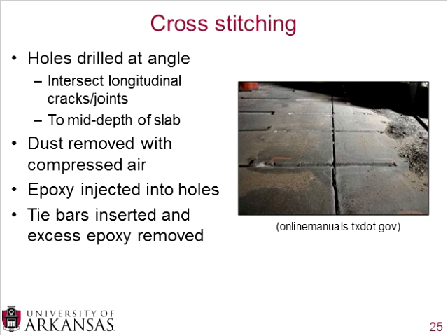So that epoxy will go from one side of the crack to the other side of the crack at an angle. Then you simply insert your tie bars and then remove any excess epoxy. And this will allow the tie bars to sit in that epoxy. As the epoxy cures, it will gain strength, and then you'll have a nice solid transfer between the two sides of the longitudinal crack.